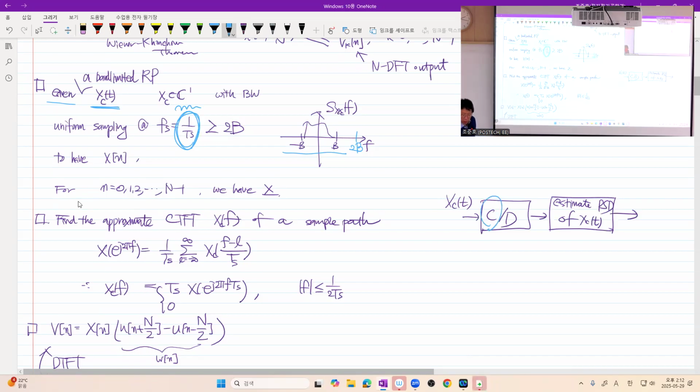So in the first part, we convert this from continuous time to discrete time, just assuming the signal is band limited and assuming our sampling rate is greater than or equal to the Nyquist rate. Got it? So conversion is done very simply. And even though this is usually a power signal, so we don't have a continuous time Fourier transform, just temporarily believe that we have some CTFT existing for this one.